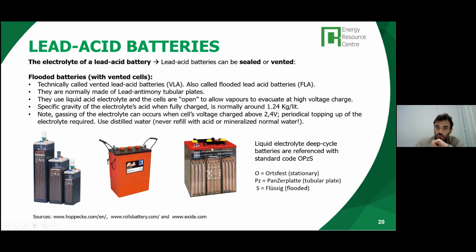Another issue, you will find these batteries noted with the standard code of OPZS. That is the acronym for some German words, which means stationary, Panzerplatte, tubular plate, flüssig, or flooded batteries. Whenever we see the OPZS, the S is the important letter here. This is a flooded battery, the one that needs to be topped up with distilled water.